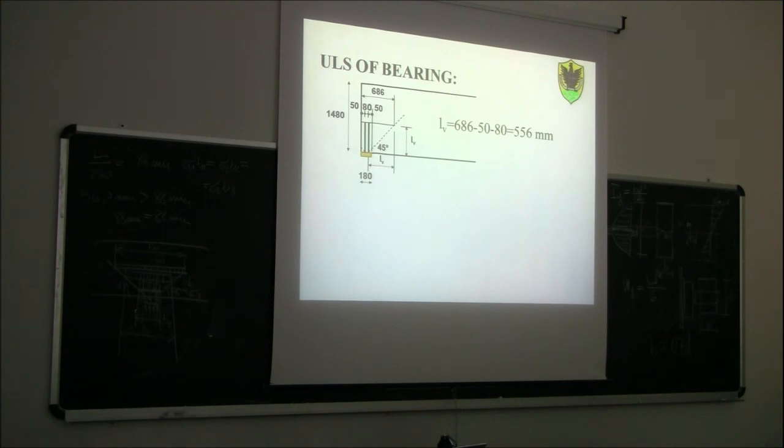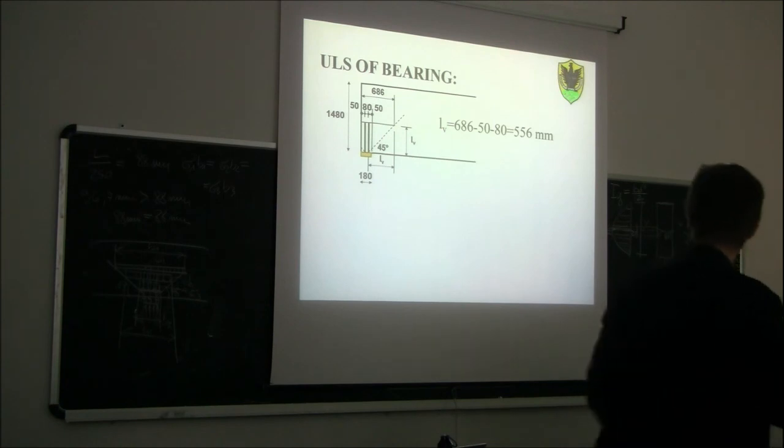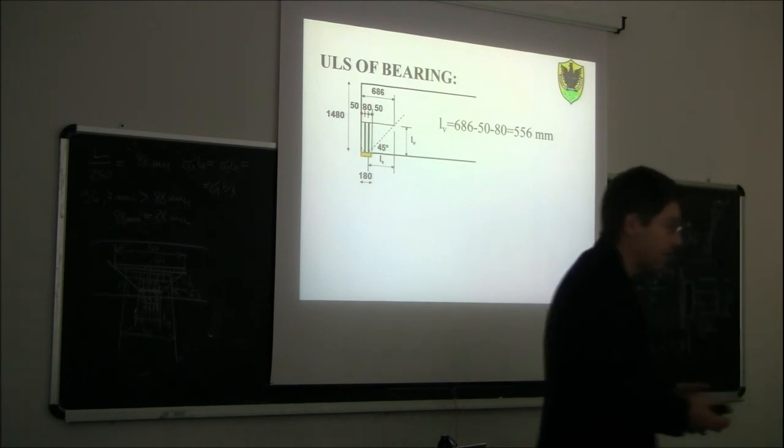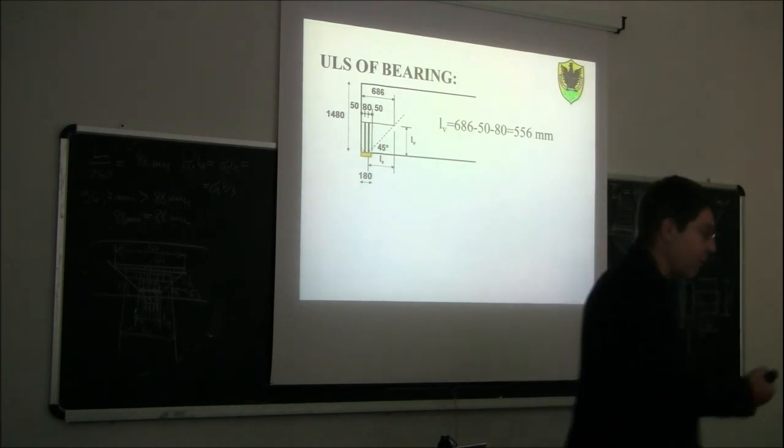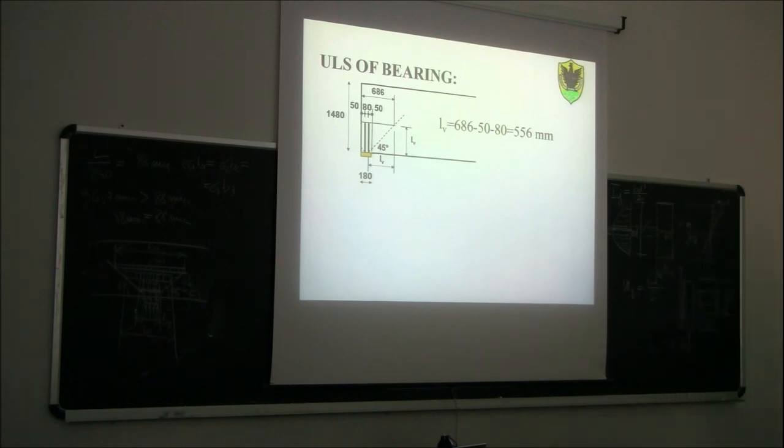In this case it's not like the Euler column that you studied in mechanics of materials, which is a column subjected to a very strong compressive force with nothing around. In this case, instead, there is something around. There is the wood, which in some way provides restraint against flexural buckling. However, you need to keep in mind that we have inserted a screw perpendicular to the grain.